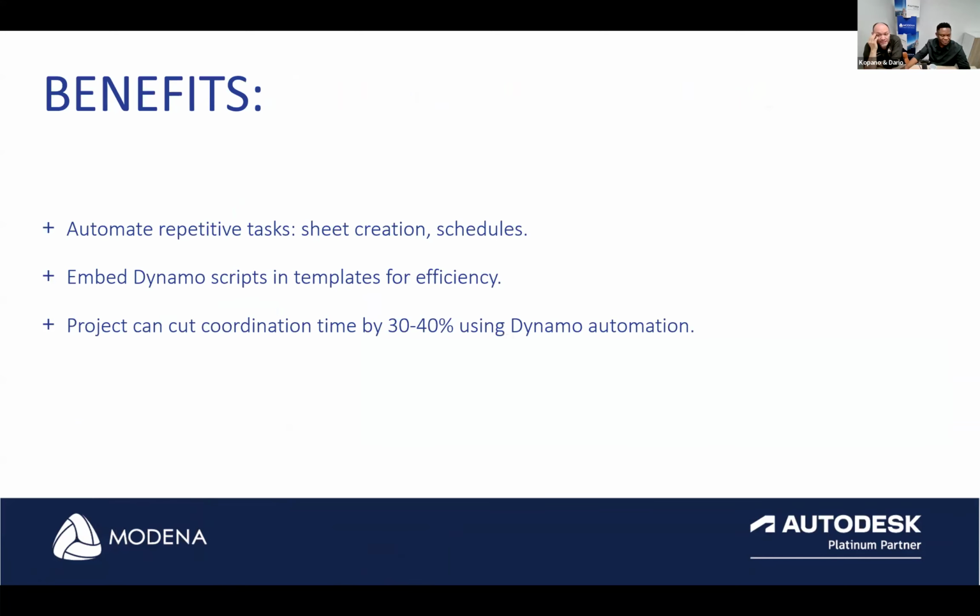Yes, benefits of Dynamo. So essentially, your sheet creation, your schedules, it automatically repeats that for you. So there's the heavy lifting. Yes. Dynamo scripts embedded in templates. So essentially what's going to happen there is that your Dynamo scripts are going to be prepared to start off on a specific base, and then consistently automate things. As an example, work sets, you can't build that into a template, but the Dynamo script can basically run it once you enable work sharing, as a very good example.